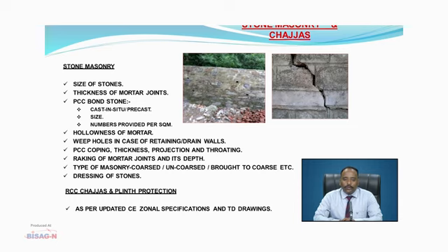The hollowness of the mortar, their random testing has to be carried out. Adequate number of weep holes in case of the retaining walls and drains has to be catered well in advance so that there is no damage to the structure later. The PCC coping, its thickness, projection and throating has to be ensured throughout the course of construction.